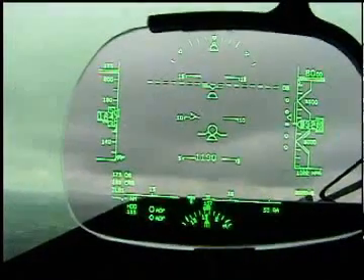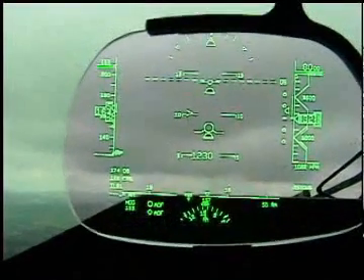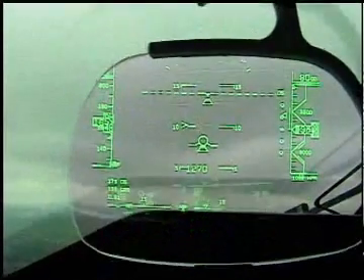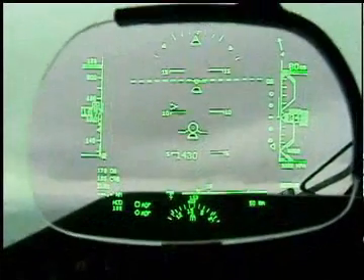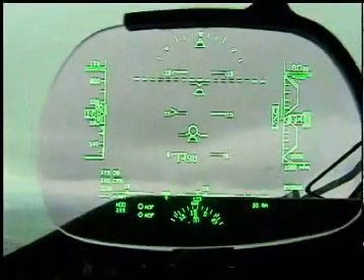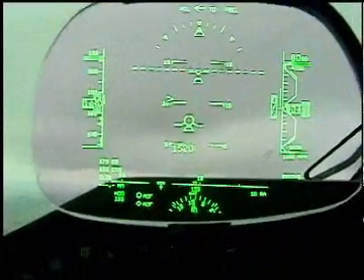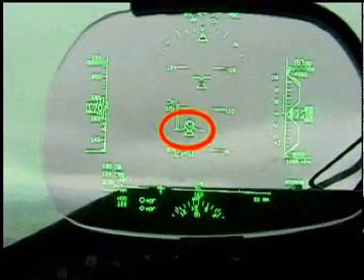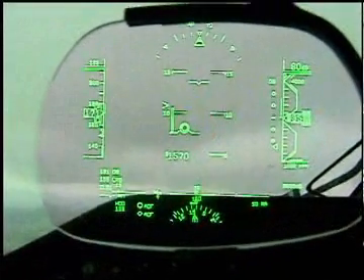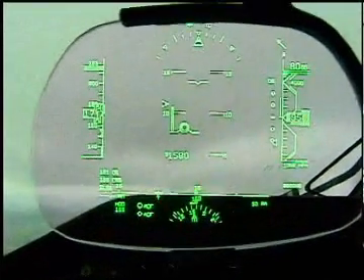During initial climb, while the flight director is in takeoff mode, the guidance cue is not displayed and the pilot maintains pitch control using the aircraft reference symbol and the takeoff go-around pitch reference line. The flight director derived guidance cue appears when the flight director mode changes from takeoff to any other mode.